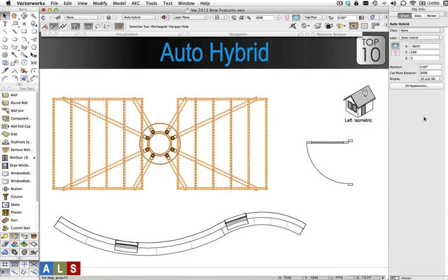and if we select the object, you can see that there is a cut plane up here. So let's move this up a little bit, say to 4 meters, and see what happens to our object. Well, the cutting plane has now moved all the way up to this point here. Let's knock that back a bit to say 3 meters, and now the cutting plane is down here, and this part is dashed above, and you have what is below. Now you can control via classes the attributes of what appears above, at the cutting plane, and below.